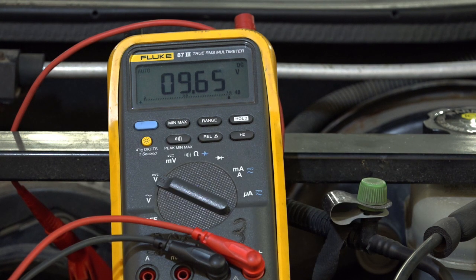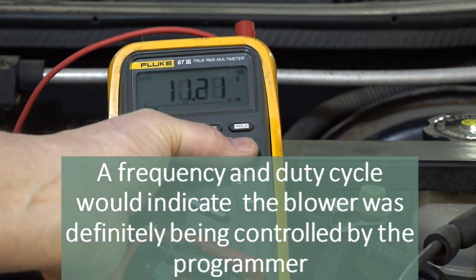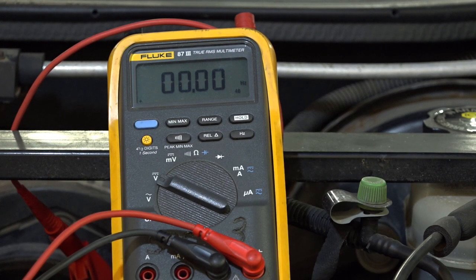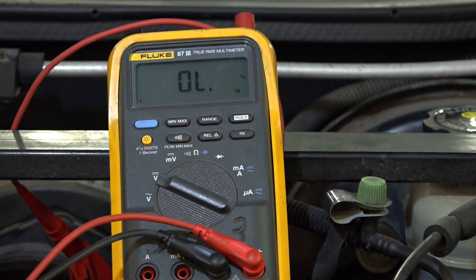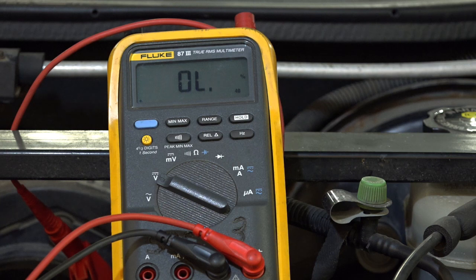So I'm going to check to see if there is a frequency or if there's pulse width. So I'll go ahead and set the meter up for that. All right, it's showing 0 hertz. Well, for a percent duty cycle. So I'm not sure at this point whether the voltage that we're reading there is actually coming from the motor or the motor controller there, or whether it's coming from the programmer.